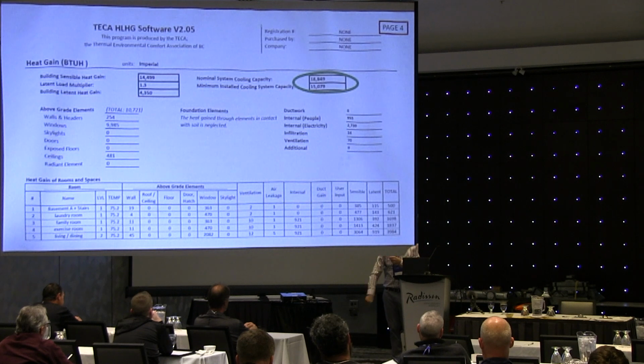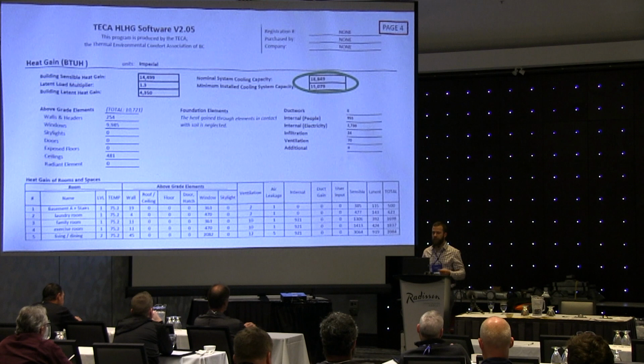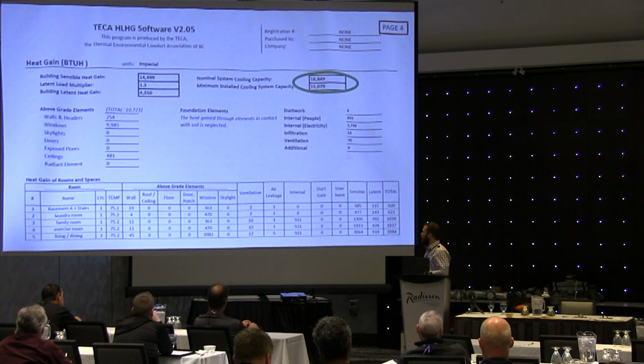And when I turn it into water, it condenses. So I'm not trying to give you an intricate understanding of this, but all you need to know is that for the cooling season, our equipment is also tasked with a latent load to deal with humidity. So that's what we say a latent load multiplier is. Approximately 30% of your sensible load: you add 30%, that's your latent load.